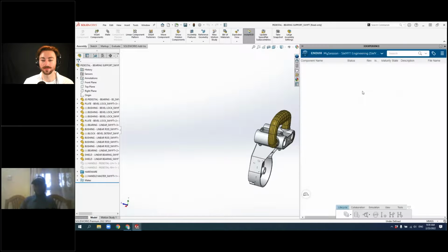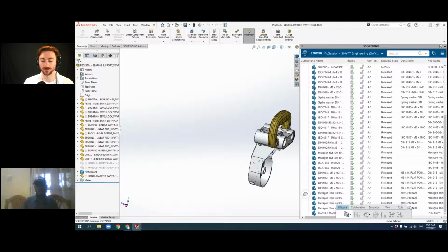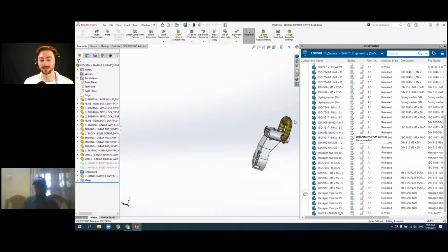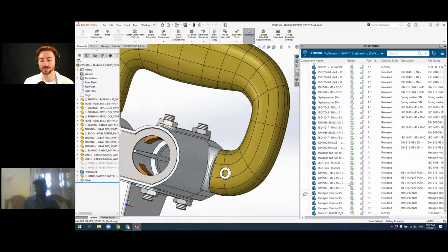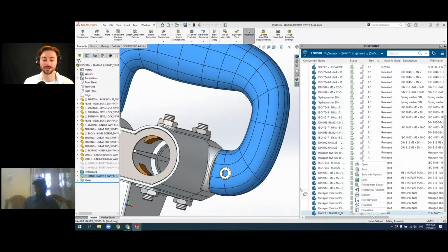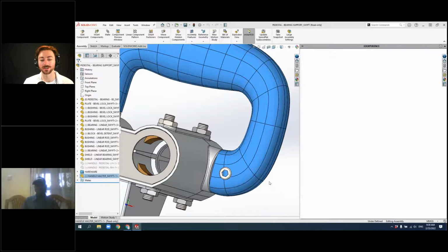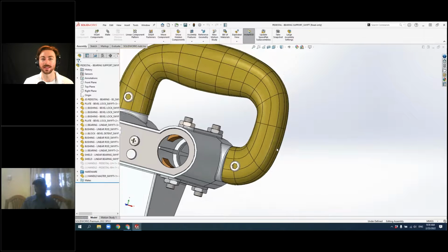You can see that in the status here, if I scroll all the way down and minimize this, give this a refresh, you'll see that I have a symbol here that a more recent version exists on 3DEXPERIENCE. So this is not a SOLIDWORKS file, but you can still add it to your SOLIDWORKS assemblies. And then if I was to just go ahead and reload that from the server, it would pull that most latest version into this session and replace it with anything I've saved.